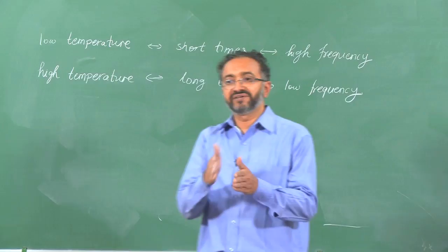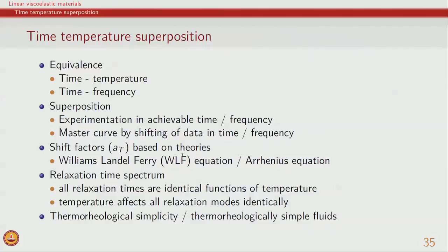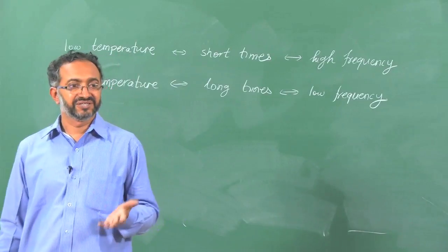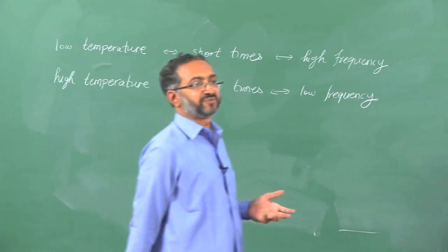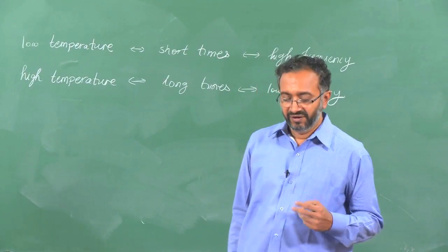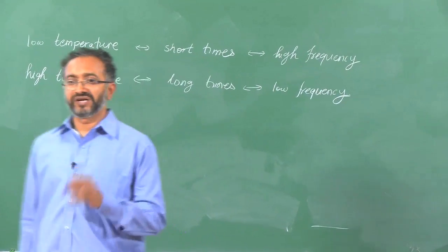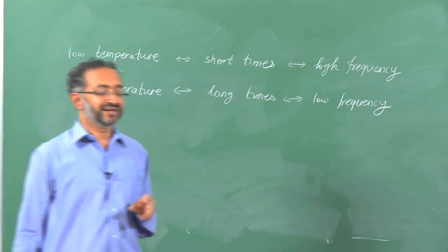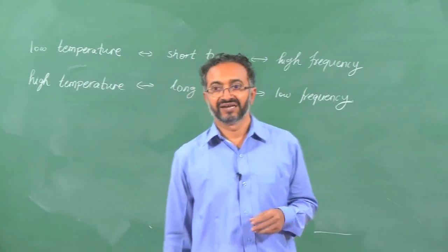So, at each and every temperature how much shift factor is used depends on temperature, and the other condition is Arrhenius. Any guess on why we have these two? And I think we talked about this in an earlier class. Whenever you have an Arrhenius process, it implies an activated process. So, what is generally observed is in more fluid-like materials and melts, you will see that the Arrhenius equation is valid.